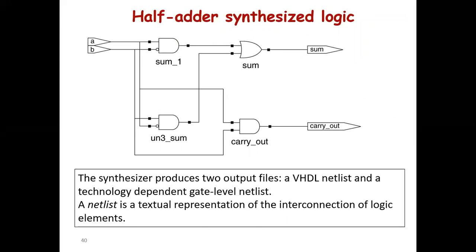This is the half adder synthesis logic. The synthesizer produces two output files: a VHDL netlist and a technology dependent gate level netlist. The netlist is a textual representation of the interconnection of logic elements.